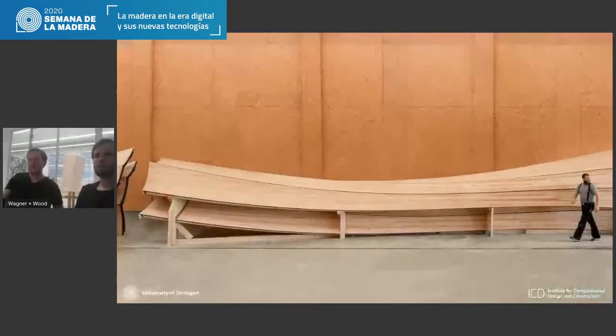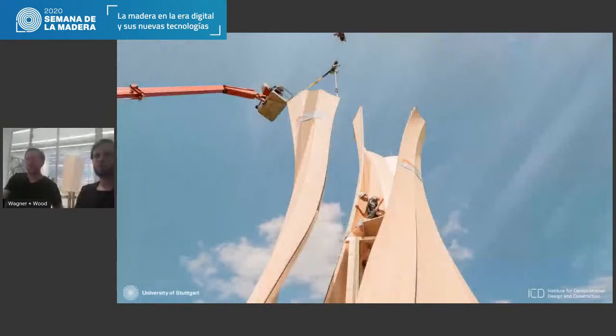They're then assembled into groups of 3 in the factory, and a weatherproofing membrane and a facade is added that's made of larch wood with a special UV wood surface treatment, which keeps the treatment transparent while still maintaining the color of the wood. The groups of 3 are then transported to the site and assembled with very minimal scaffolding by a team of only 4 workers in a single working day.